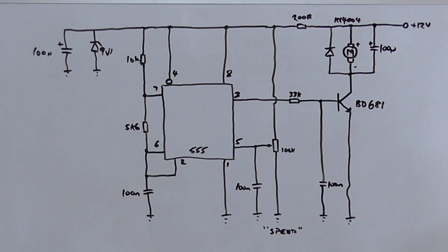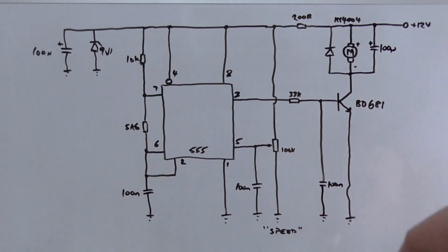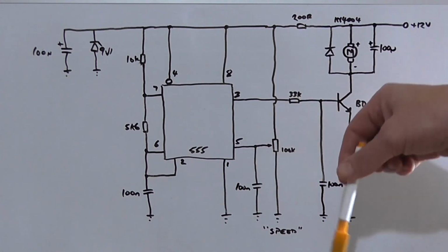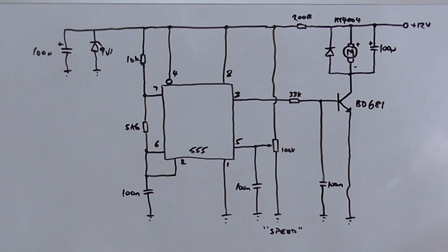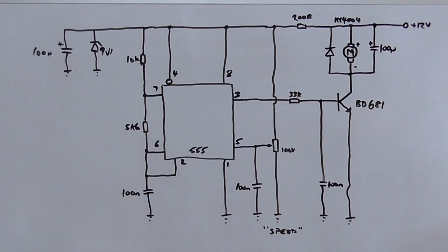Keep in mind that when you vary the duty cycle of the square wave, the frequency at the output is going to vary. So the basic operation is, when this pot is rotated fully anti-clockwise, the control voltage is 0, therefore the output is 0. As soon as the pot starts to increase in its rotation, the control voltage starts to increase and the duty cycle starts to change.